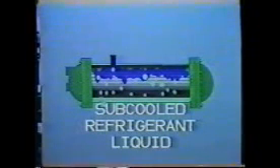Hot refrigerant vapor enters the condenser shell at the top and flows around all the tubes. As the vapor comes in contact with the cooled tubes, it condenses on the outside tube surfaces. The droplets of refrigerant liquid fall off the tubes down to the bottom of the condenser. As cooling continues, the refrigerant is subcooled, but it is still at high pressure.